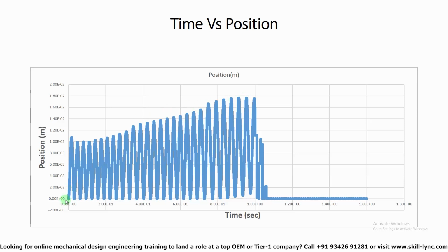So the reason why it's alternating in the first place is because that is how a pressure relief valve is supposed to work. So the spindle goes up to a position where it can relieve enough fluid pressure so that the pressure in your main line is actually reduced to a point where the spring force actually dominates and pushes back the spindle, right? Not just the spring force but also the mass of the spindle. So this process keeps on occurring.